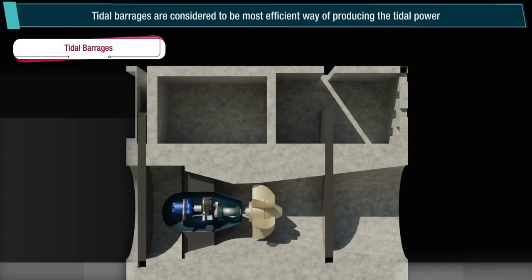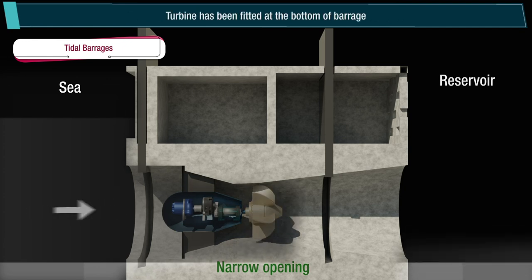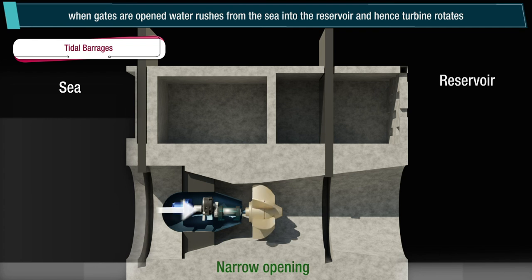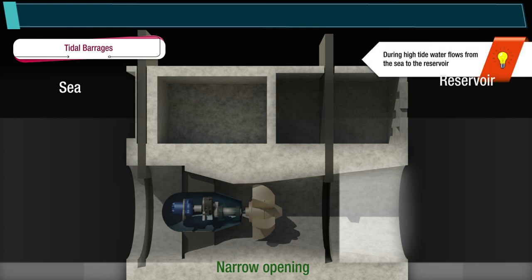Tidal barrages are considered to be the most efficient way of producing tidal power. In this case, a reservoir is made on a narrow opening of the sea, and when there is a high tide, the gates of this reservoir are opened. A turbine is fitted at the bottom of the barrage. When gates are opened, water rushes from the sea into the reservoir, and hence the turbine rotates. When the turbine rotates, we get electricity from the generator, which is coupled with the turbine. Note: during high tide, water flows from the sea to the reservoir.